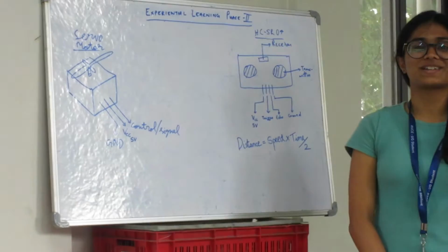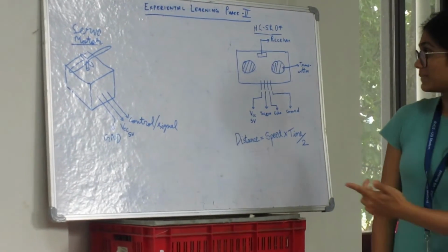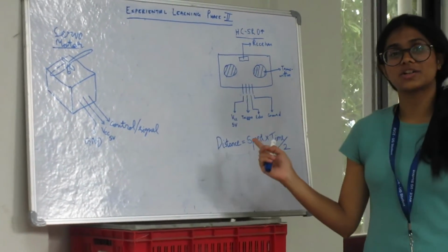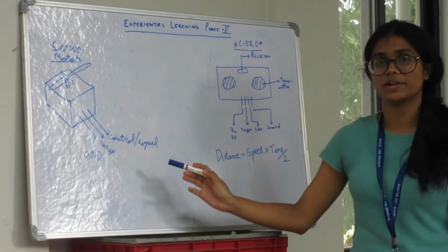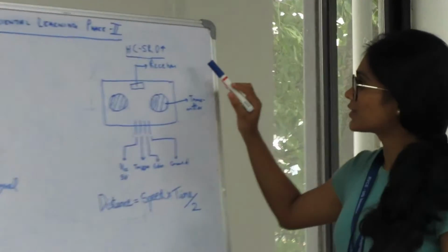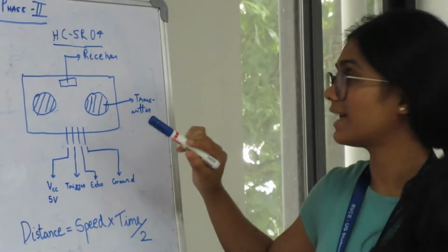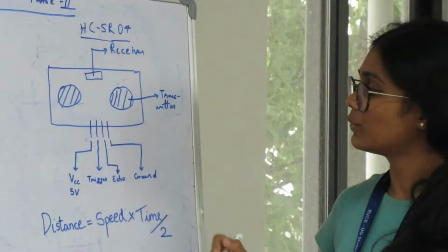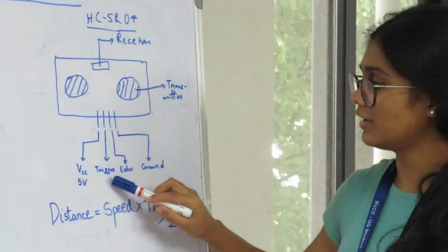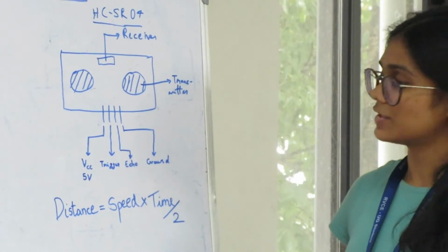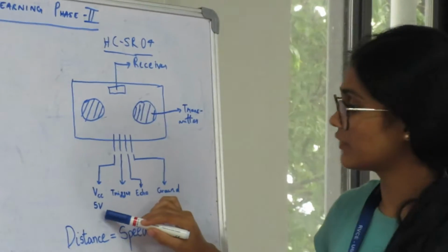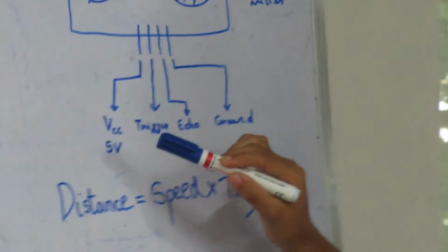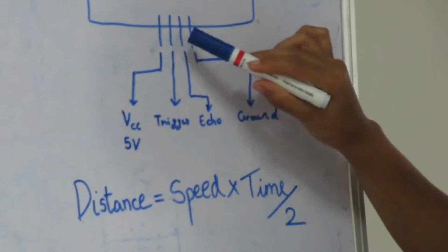My name is Harush Elharki, and I'm going to be explaining the working of the ultrasonic sensor and the servo motor today. So the ultrasonic sensor, which is HCSR04, has 4 pins basically, which are VCC, trigger, echo and ground. So the VCC pin is given 5 volts by the Arduino board, and the second pin is the trigger